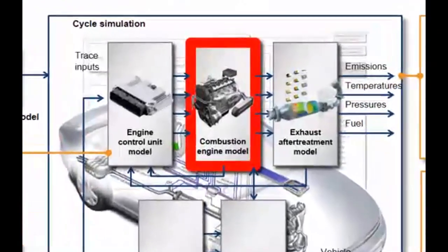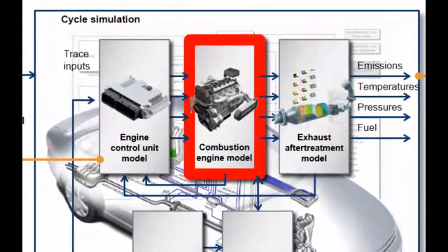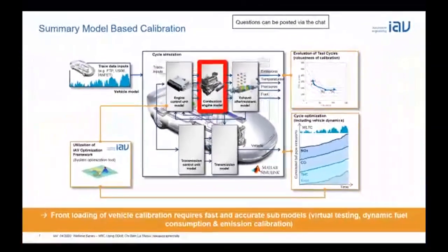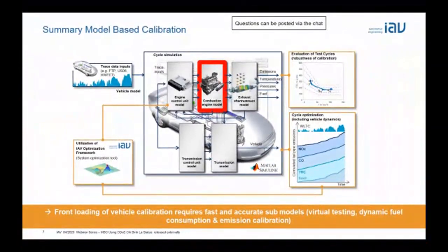Because of this, a further application of the dynamic DoE model is to be able to link it to the actual control strategy in a model-in-the-loop environment. The dynamic DoE model serves as a fast and accurate plant model to help develop the ECU control strategy, permitting the use of optimization routines to calibrate the parameters offline without further engine testing.